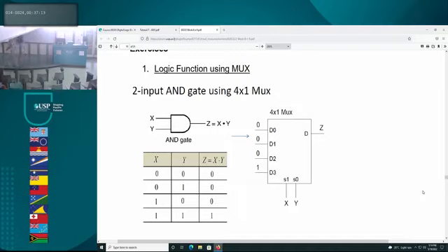So let us say you walk into the lab and you ask for an AND gate as shown, and the technician says, sorry, we're out of AND gates, and you can always say, okay, I want to build it. What's one option? You can build an AND gate using NAND obviously, or you can build it using NOR, but you can also build it using a mux, right?